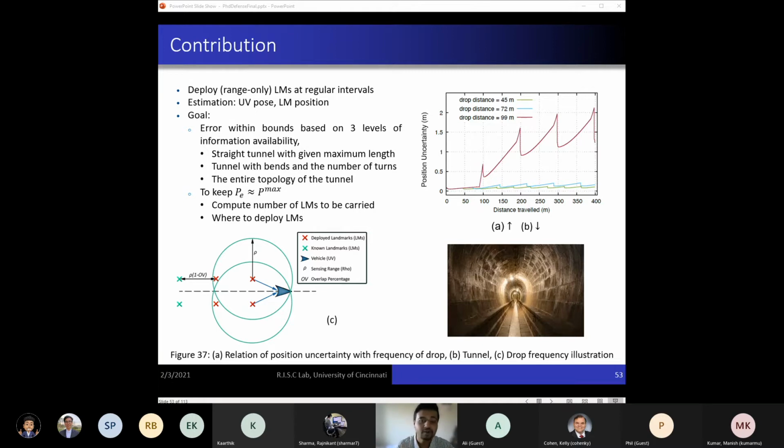That is, it is not receiving measurements from any landmark. Therefore, the corresponding positional uncertainty value happens to be significantly higher. So these are some of the important observations, as this plot reassures the importance of having measurements. Our goal is to keep the final estimated PE, or positional uncertainty metric, value close to the user-defined Pmax value, which is the uncertainty associated with the position error.